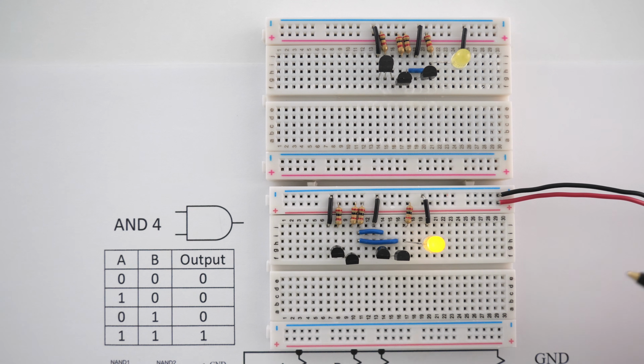The only case that I can think of where you would want to use NAND gates to build an AND gate would be if you had an integrated circuit that had, say, 4 NAND gates built into it. You could then use 2 NAND gates to build an AND gate, and you wouldn't have to have a separate integrated circuit for each type of gate.